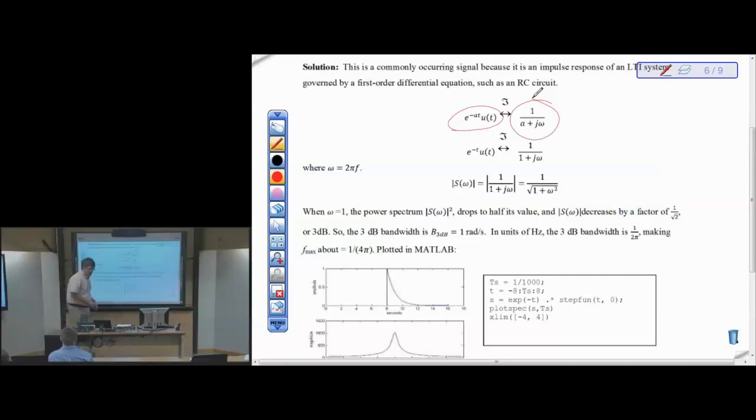What's interesting about this is that whenever you see a decaying exponential like this, you can pull out the useful information right away in terms of frequency content and also time response. That useful information is tau. Tau is a time constant. It tells you the delay through the filter in the time domain, if this were a filter.